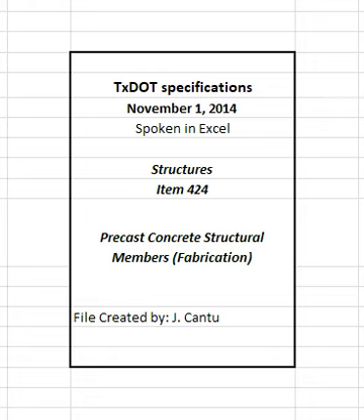Seal cracks in I-beam ends exceeding 0.005 inches in width as directed. The fabricator must decrease the spacing of bars R and S in I-beam by providing additional bars to help limit crack width. No less than 1 inch's clearance between bars will be permitted. The fabricator must take approved corrective actions if cracks greater than 0.005 inches form. All work, material, and engineering related to these cracks will be at the contractor's expense.